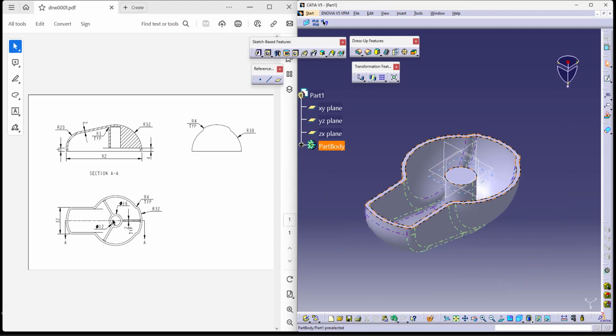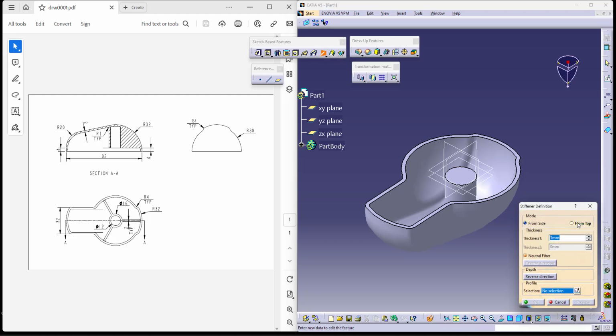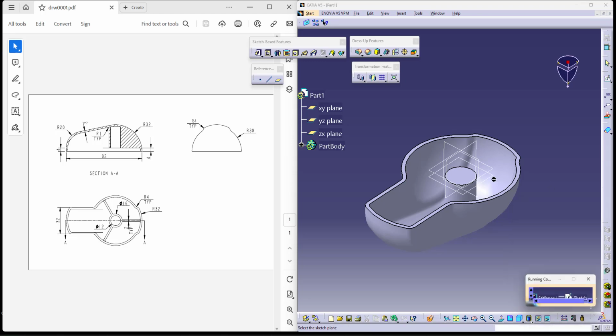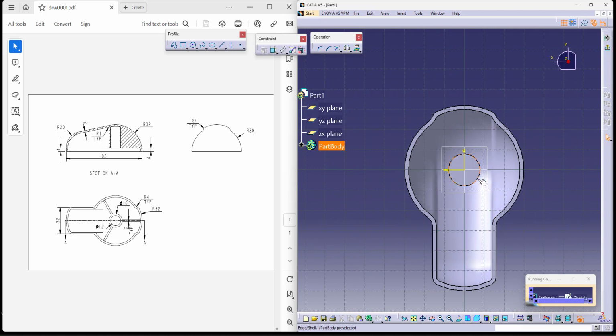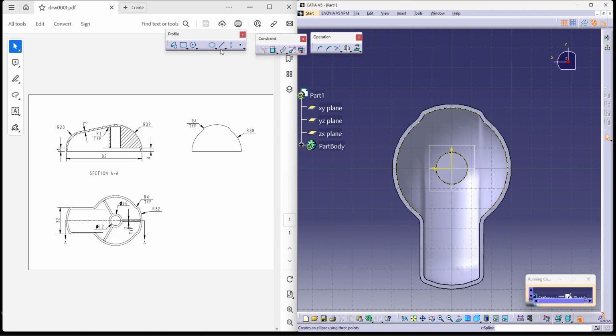Similarly, there are supports. As you can see, we can do them as well. We have a stiffener command which can help you do that. You have to give it from the top, because the supports are from the top, and then you can start making your sketch using the same thing. Here I'd like to flip the model because I want to use these references and these references. Now, let me select all of them in one go and then use them as my references, and then start making my lines. So this is the first line which starts from here.